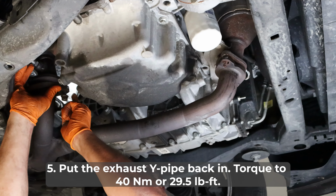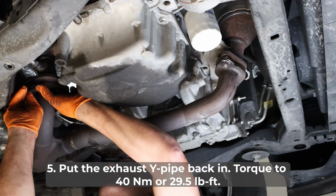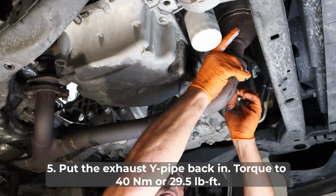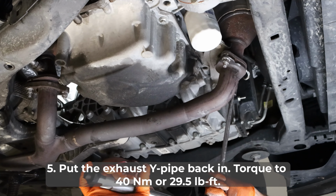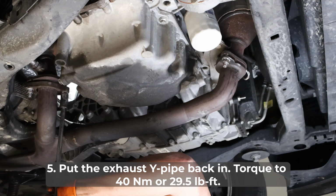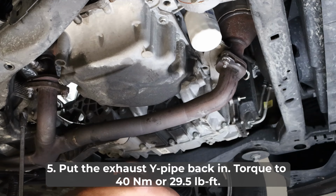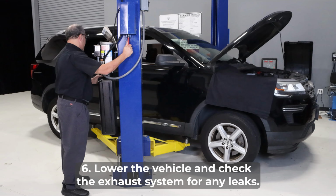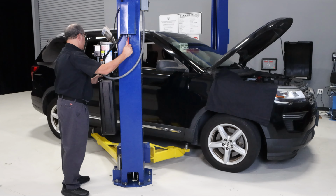Go ahead and put the exhaust Y pipe back in. Once everything's together, lower the vehicle and check the exhaust systems for any leaks.